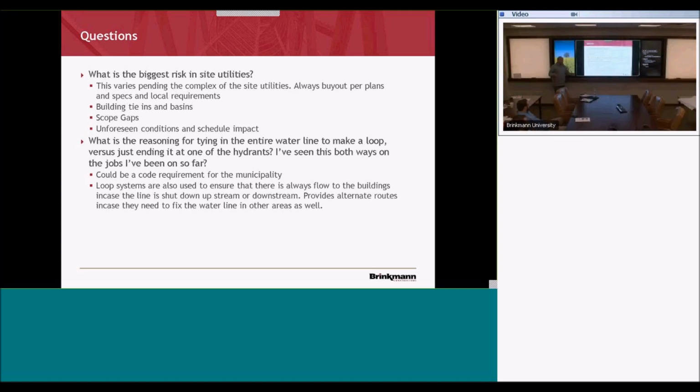It's a vacuum truck with a water line and a big hose about yay big. They put it down on the ground. It uses water pressure to make the hole, sucks it back out, and they haul it off. Once they get down in there, they can even turn it a little bit to expose an area, and you can find what utilities are there, and it doesn't tear up that utility. And Jack, can you go over who calls for locates?